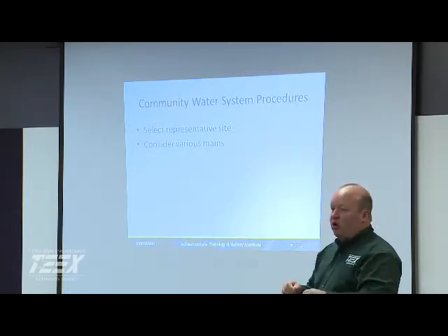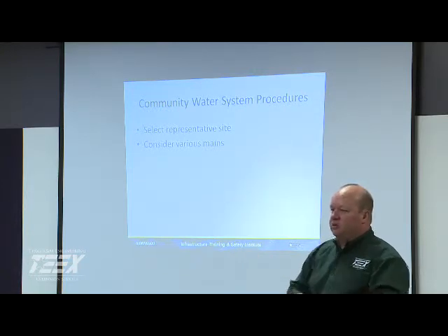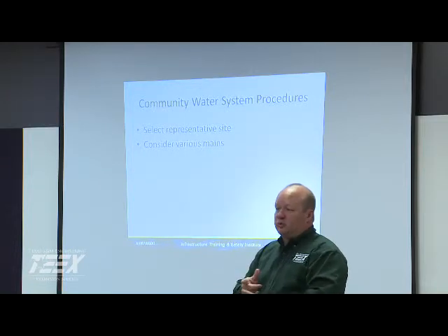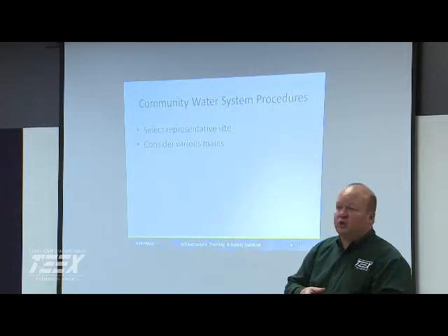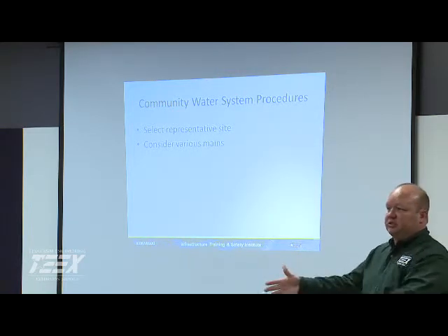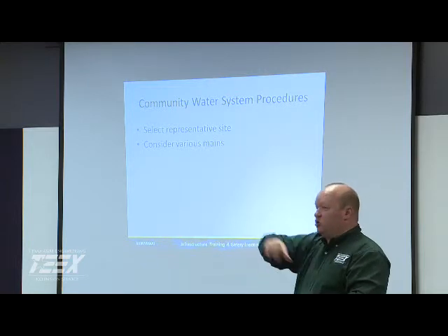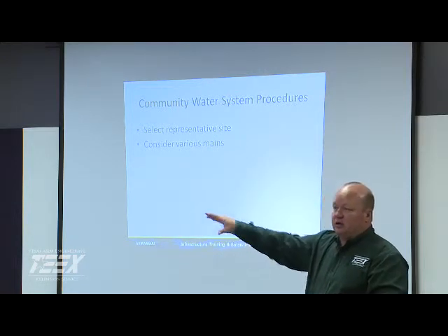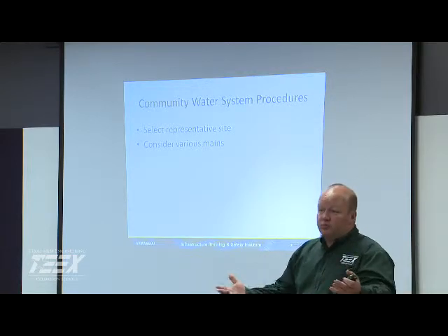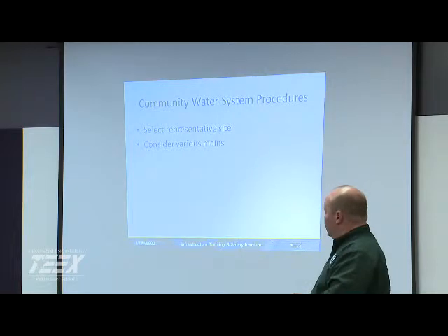And there was a real neat article on, and not everybody has the ability to go and model your distribution system, but just something as simple as regular valve turning can help you understand what should be open, what shouldn't be open. Because it's easy if somebody goes into a repair, closes a valve, and now you've got a leg that used to be in a loop, now it's a dead end. And now you start asking, why are we having these low residuals out here? You might have a valve closed out in your system, something real simple.